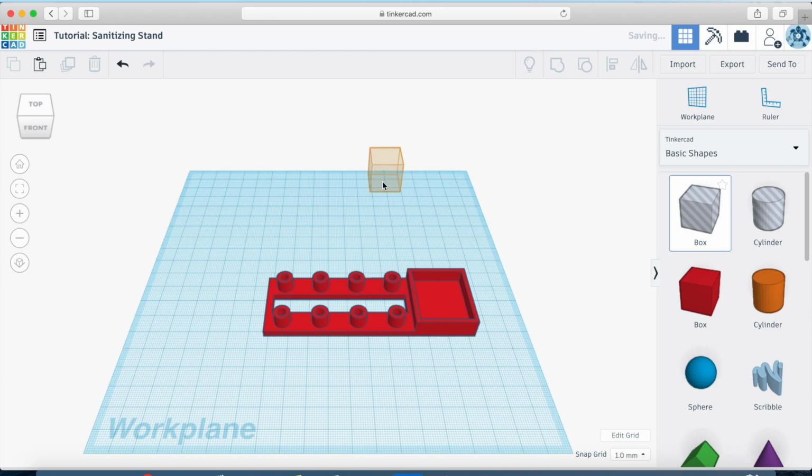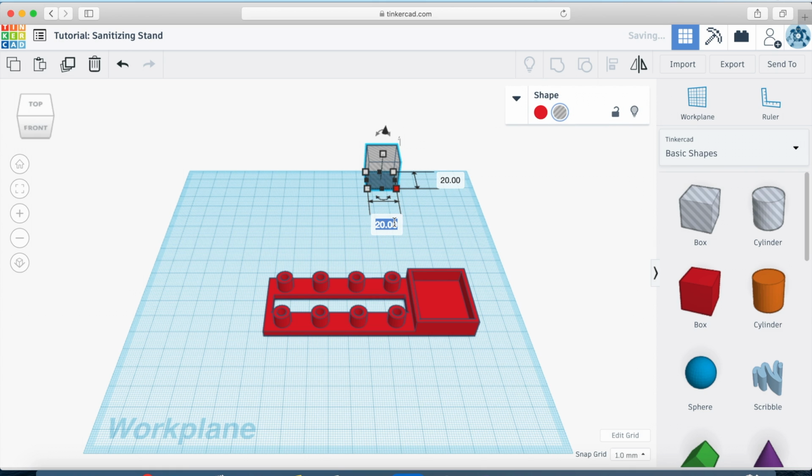Now drag in a box cutout and dimension this to be 9 millimeters by 40 millimeters with a height of 20 millimeters. Using the cone, drag it up one click, or you can drag it up many clicks and change that value to 1. Now copy and paste this cutout twice, so you have 3 of the same size cutouts, each 1 millimeter off the work plane.